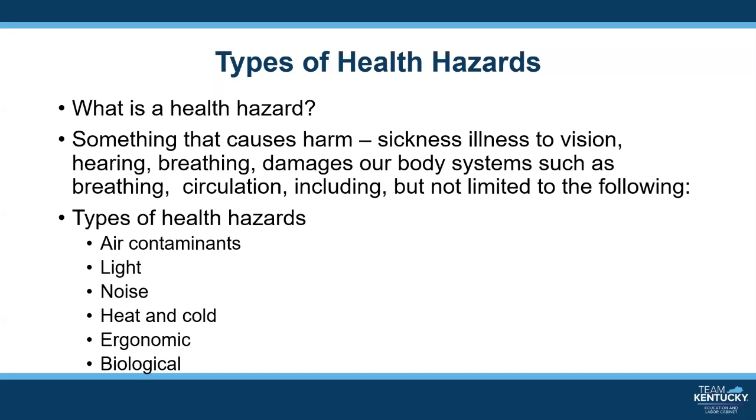If the worker breathes in the metal fume while it's hot, it then cools when it is inside the lungs, nose, and throat. When the welding fumes are hot, they are in the air, but when they cool, they become dust and settle on work surfaces, clothing, and skin. Workers can later touch these surfaces and get the dust on their hands and transfer it onto their food, cigarettes, and things like that, and end up eating or breathing them in later on. We will discuss the details of cleaning up these contaminants later.